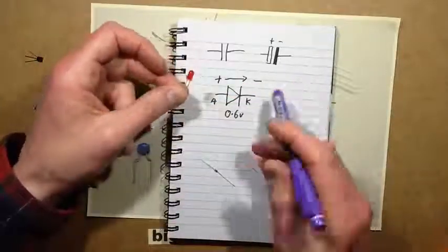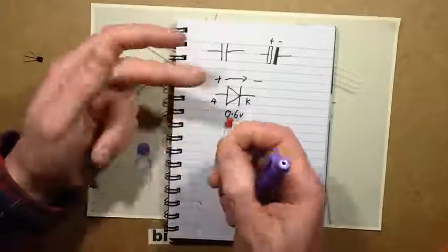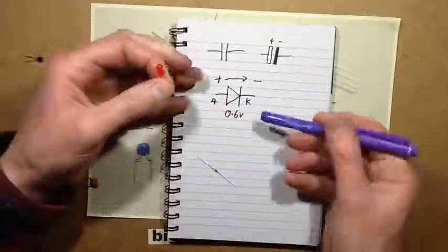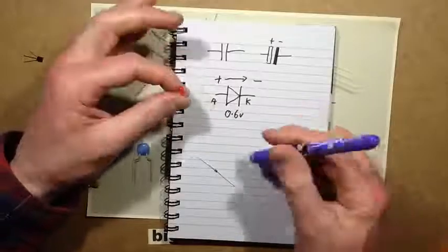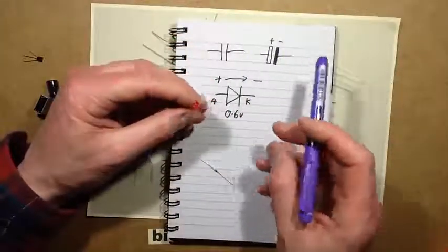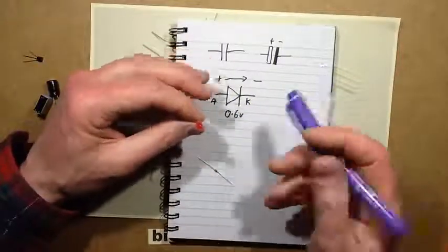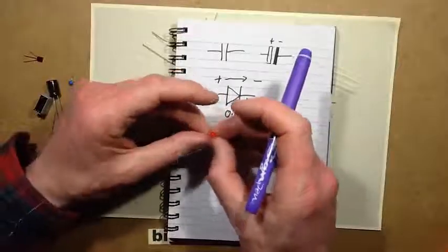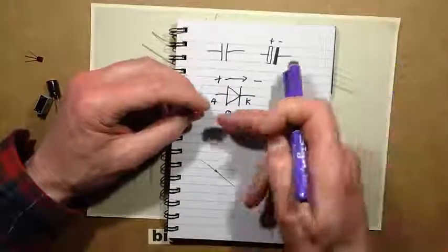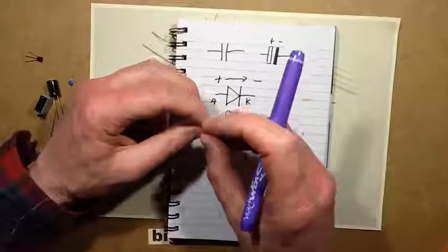But one of the things you have to note with an LED is that, because they're optimized for emitting light, they don't have a high reverse blocking voltage. It's usually just about 5 volts. So if you were to connect the polarity wrong and exceed about 5 volts, in the case of white, blue, green LEDs, it may damage them, but with red ones, they may end up just conducting in the wrong direction, but not lighting, and not suffer damage.